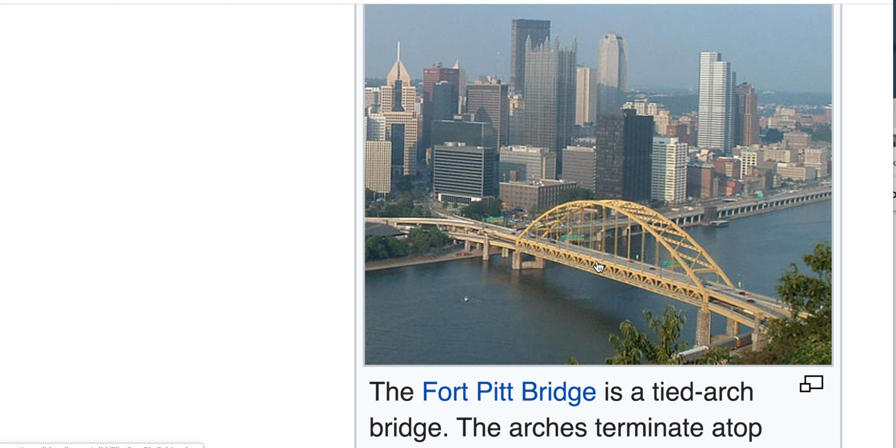Now imagine I was down here, and I could pull down on this, and these weren't connected right here. No connection, and no connection. This was still lying on top of here, with no connections besides right here. As I pull down on the center of the structure, this would still have the effect of pushing the ends out, correct? Remember, they're not connected there. So you see what happens when the load comes: it just wants to naturally push out on the ends. So what do you do? Well, you tie it back.